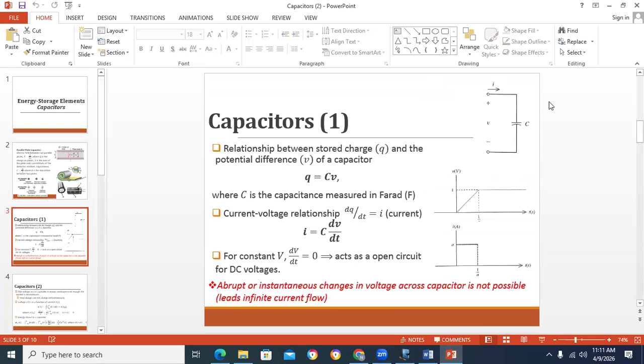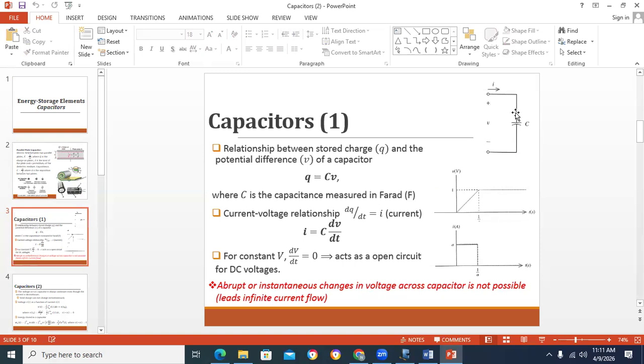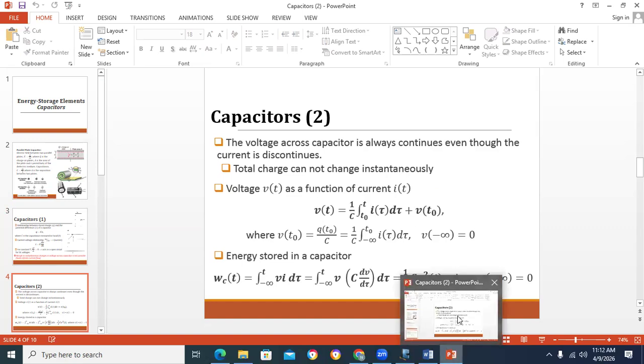So you can see that this equation we write when the I is going to the capacitor. So I is equal to C dV/dt and V(t) is equal to 1 over C integral of I(t) dt, like this. This equation is when the current is going to the capacitor, but now the capacitor is discharging. That means the current is flowing from the capacitor. So this I will be minus. So this is not plus I, this will be minus. Okay, so that is it.